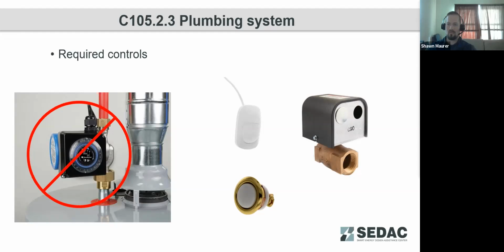For a dedicated return circulation loop, where the hot water system has its own dedicated circulating loop, the most common place to see that control setup is a flow meter installed on the cold water tap coming into the hot water tank. As that tank needs to refill, as hot water is drawn out, then that flow meter will indicate that there's been a demand, and that circulating pump will then kick on. And should kick off once the circulating loop has met its set point temperature again.